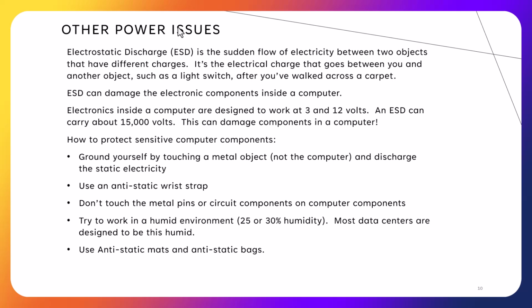That charge, if it happens on a PC, can damage components within a computer. These components within a computer are designed to work at 3 and 12 volts. The electrostatic discharge can carry up to 15,000 volts, and that can damage the computer. So how do you protect yourself against ESD?